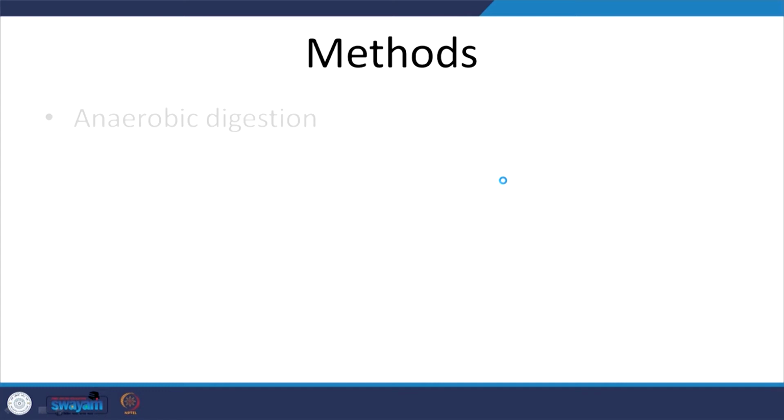So, different methods. One is anaerobic. Firstly, why anaerobic? And again note that this is widely used. Sludge, especially the organic sludge here, has a lot of organic concentration. So, if you want to do it by aerobic, you need to provide oxygen. If you are doing it within a controlled system, yes, that also can be done, but again you need to put in energy.